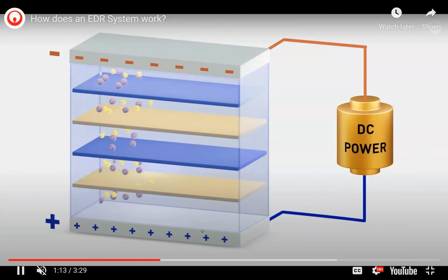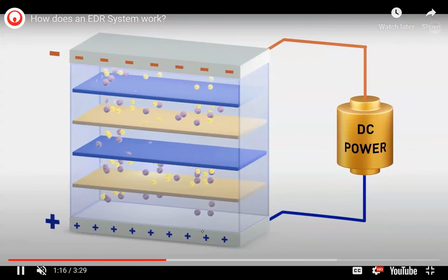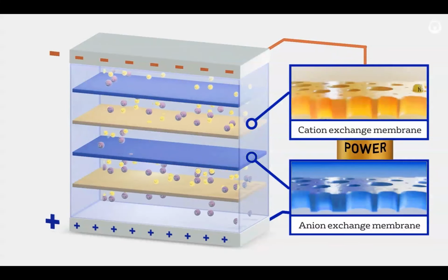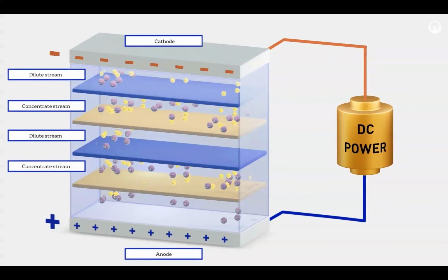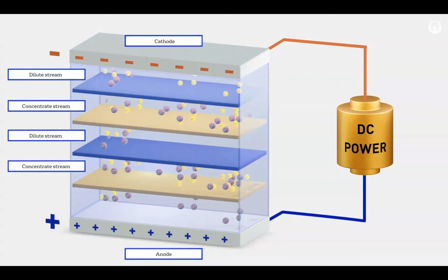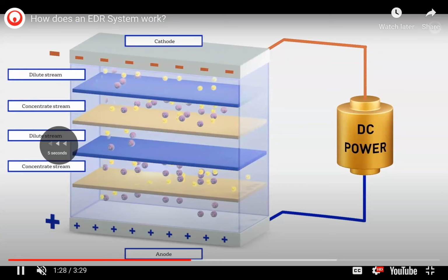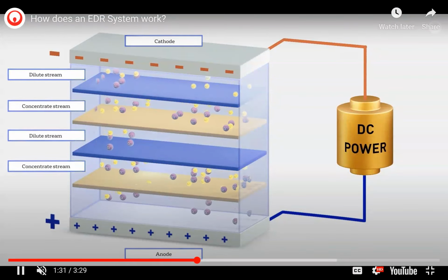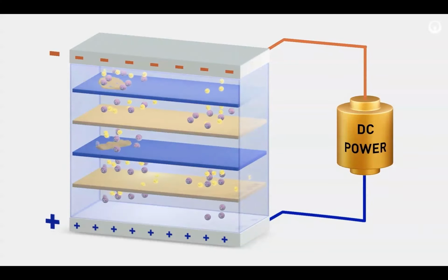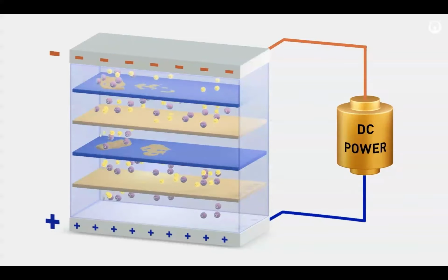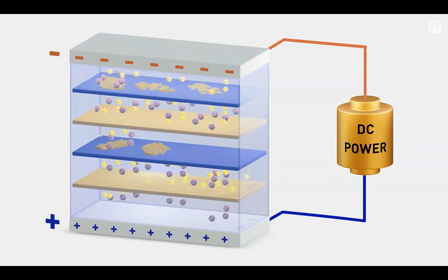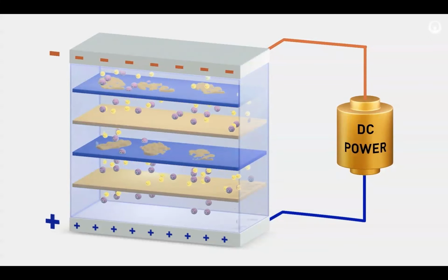So you can see here, first electrodialysis, both are the same, but we are just changing one membrane to another polar charge, so that the fouling, the clogging, can be opened and then we can continue the process. That is the electrodialysis. So here Cl minus is passing through the blue colored surfaces, and in the brown colored surface Na plus ions are passing.